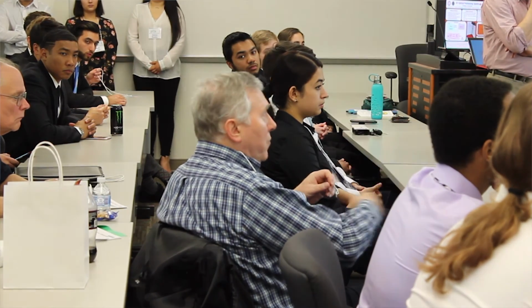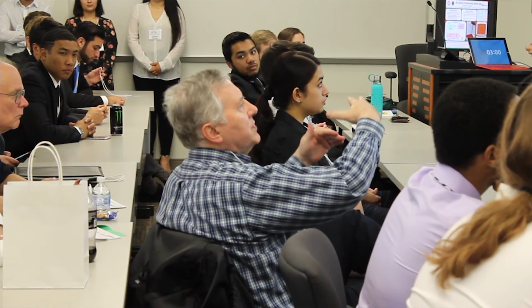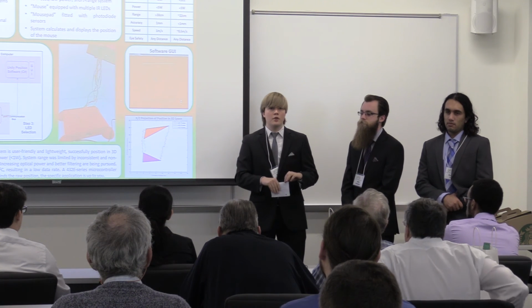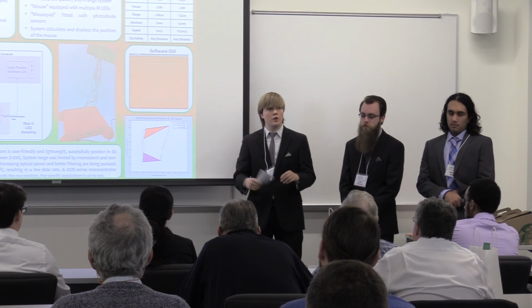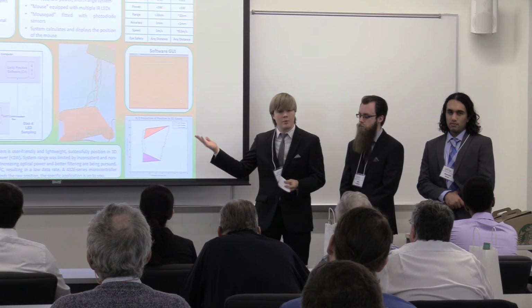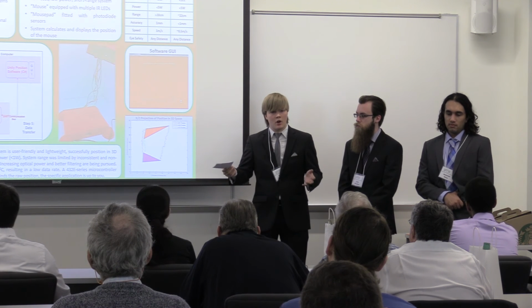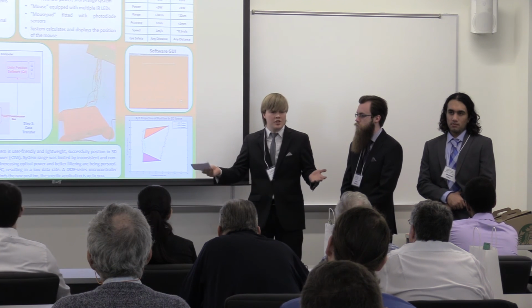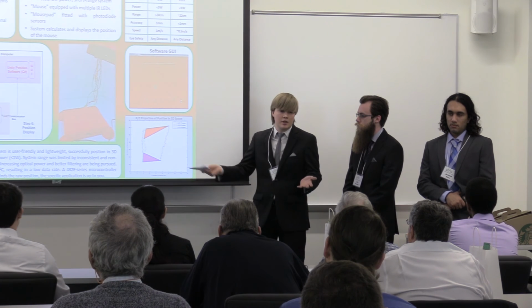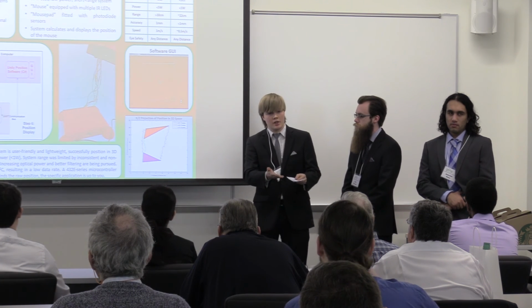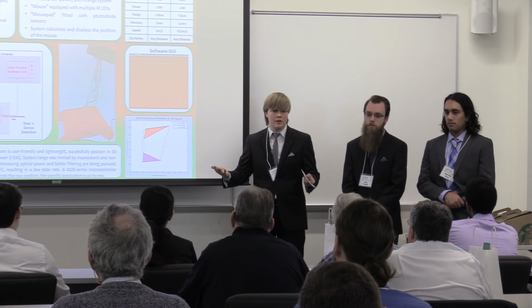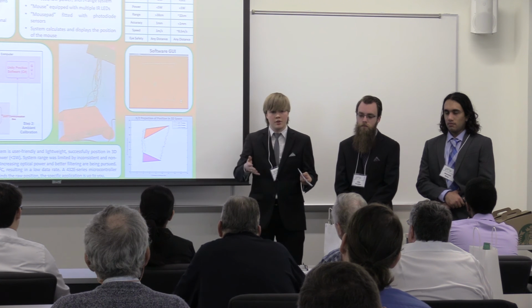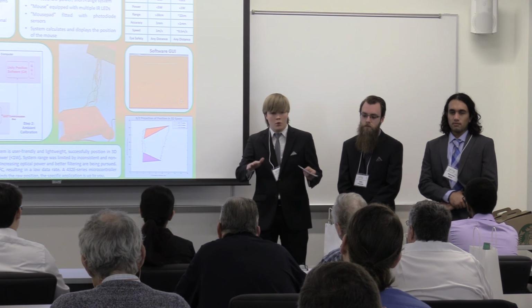So your technique is you periodically recalibrate to compensate for whatever the ambient light is. We found that we didn't need to periodically recalibrate. It's hard to believe, but okay. Yeah, because when we left this running for perhaps an hour and then came back to use it, our calibration target is, we'll just say, 100, because if you're not using the sensor, that doesn't really mean anything. But our calibration target is 100, and normal operation creates intensities of around 4,000 to 8,000. And after we left it running for an hour and returned to it, the baseline intensity readings were still below 200.